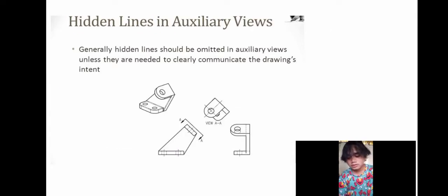Hidden lines in auxiliary views. Generally, hidden lines should be omitted in auxiliary views unless they are needed to clearly communicate the drawing intent.